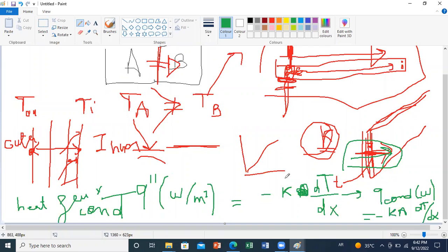So in this case, we can see that the higher the conductivity is, the higher will be the flow rate between the inner and outer space. So for example, in the building envelope, we tend to select materials with small conductivity in order to not have heat losses through the envelope.